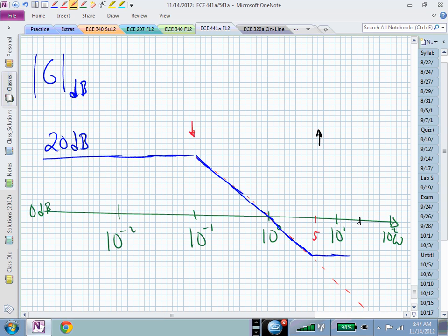which is actually going to occur at 20, and is the log of 2.3 or 1.3 for 20. So now we have 30% of the distance between 10 and 100 is 20. And so now we are flat until we reach that frequency, and after that frequency, nothing more changes, and we're just going down at 20 dB per decade. So this is now our magnitude plot.